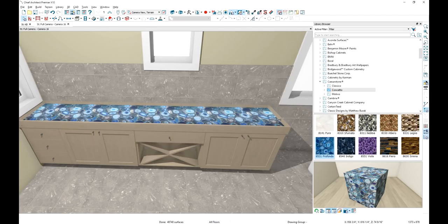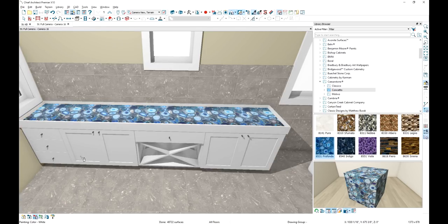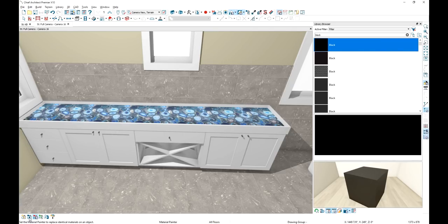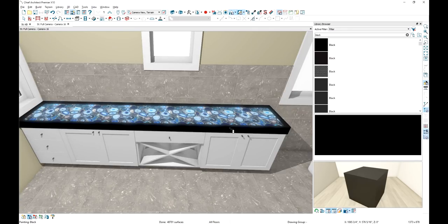And now I'm going to go ahead and change the colors for the cabinets. Let's use the material Eyedropper, pick up the casing color, and in this case I'm going to apply it in the room mode and change all colors of that same alder color to white. And then I need to find a black color. Let's just search in the library here for a black. I'm going to use that black and change my scoping back to the object, and we'll just apply it to that top box. And now you can see the way that that looks.